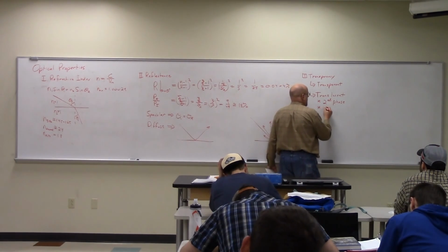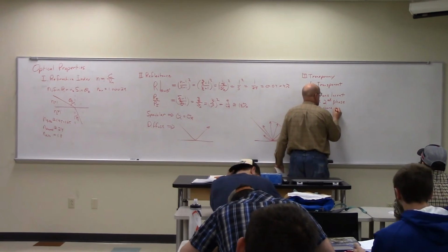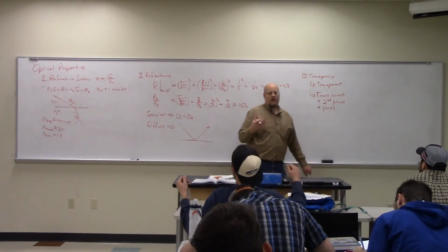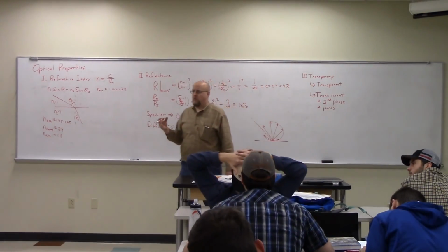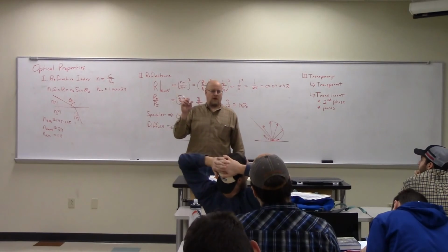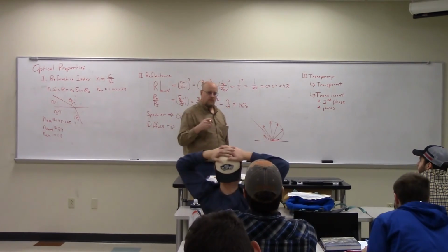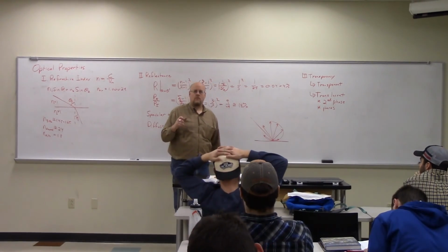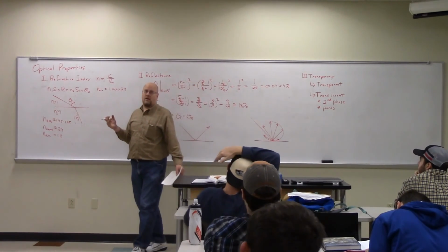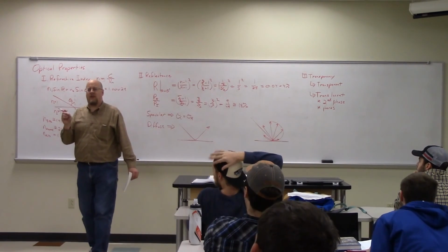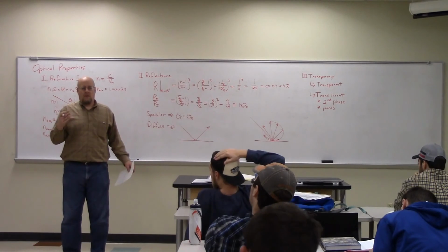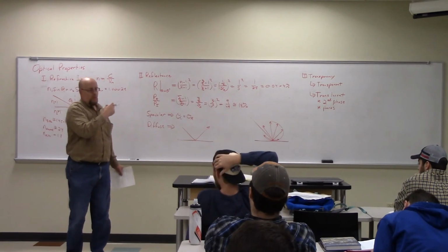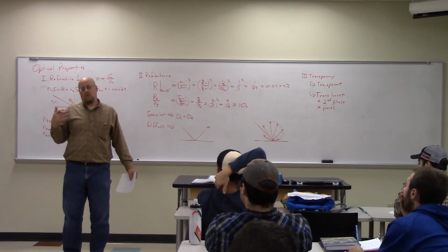Or it can also be caused by pores. So if I have a porous piece of glass, it will look translucent because of little pockets of air inside there. That's because the air has a dramatically different index of refraction. So it would take less porosity in an equally thick piece of glass than it would second phase materials in order to cause that scattering.